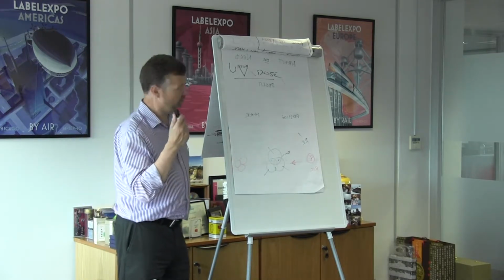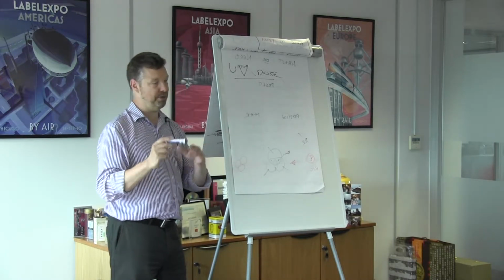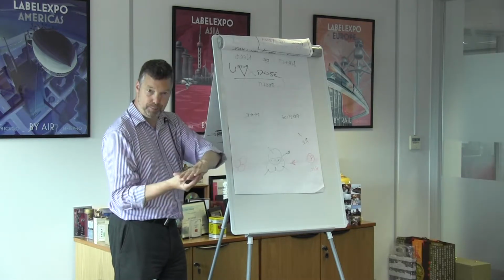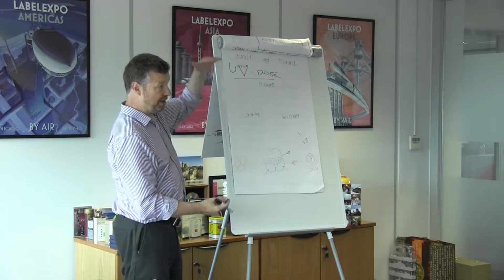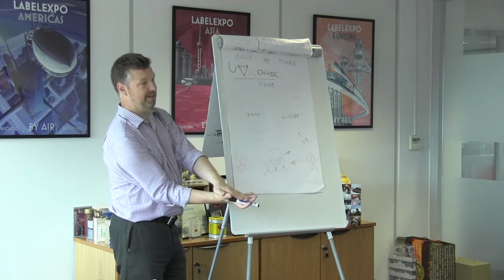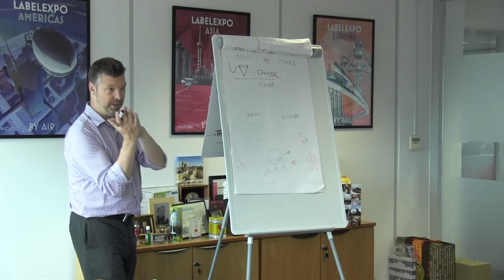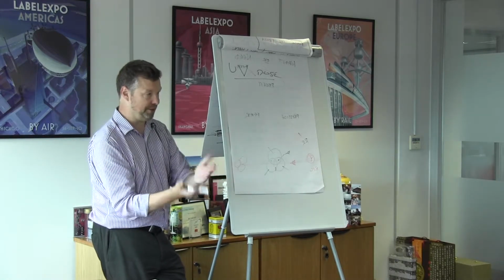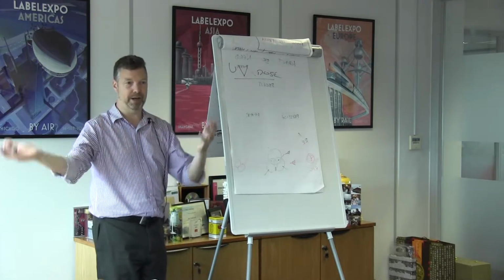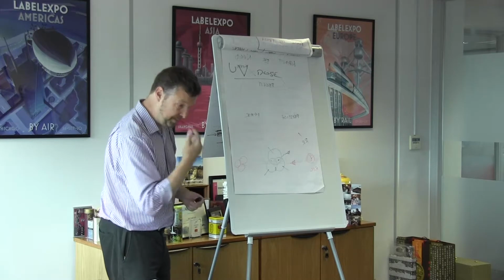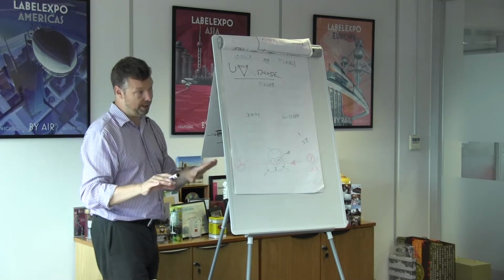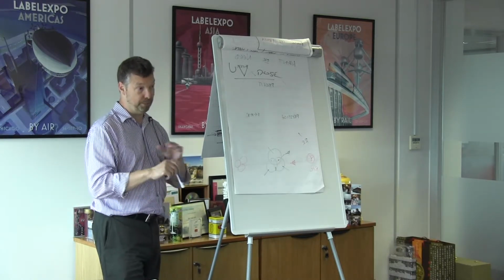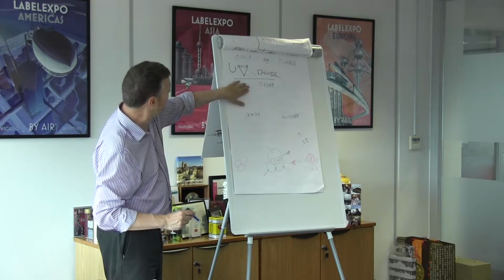UV is important because, if you remember, thinking back to what we said about UV, it dries instantly. Any print speed, because it's a chemical process, not like evaporation. So as soon as that UV hits those little buzzy bees, that ink immediately becomes a solid film. And it means you can run a press at any speed. You don't have to worry about the ink not drying before the next ink comes down onto it, all this kind of stuff. You don't have to have big drying tunnels like you do with the water-based presses. So UV is a fantastic, efficient way of drying inks at a very fast speed. There are issues, as we know, with the migration problems and stuff, but I'm not talking about that so much here.